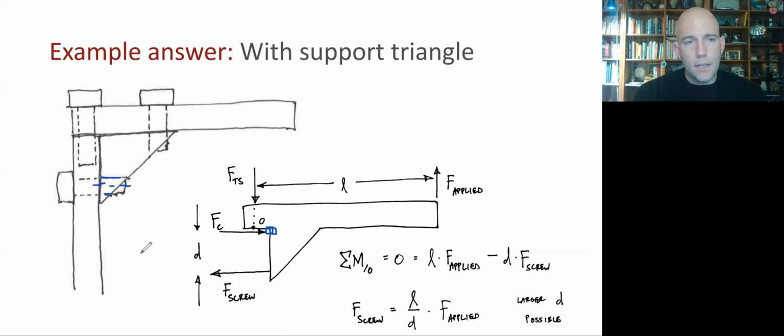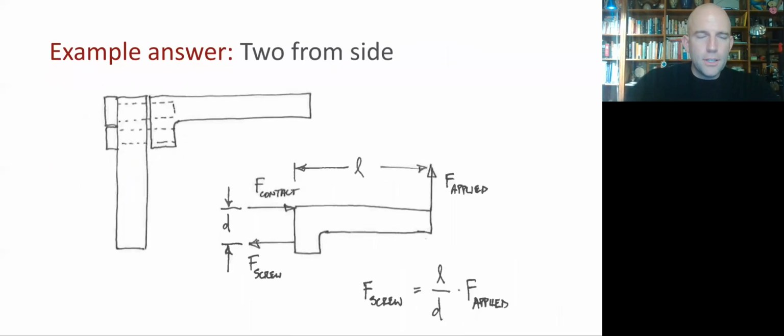Up here in this example and in the previous one, we can see it in the previous case as well. Sorry, having a little trouble changing slides. If we try to compress that screw, it won't produce any force. It'll just slide back out the hole, right? So this force at the top corner here isn't coming from the screw. It's coming from the 2 surfaces pushing on each other.